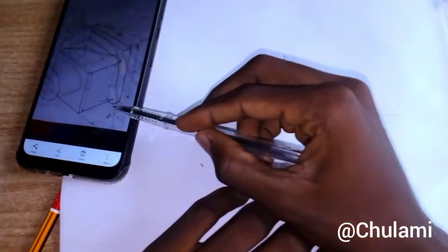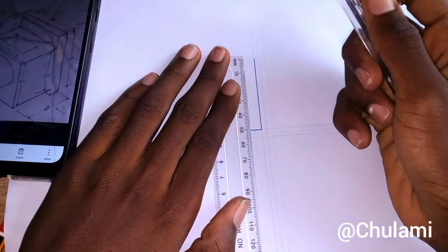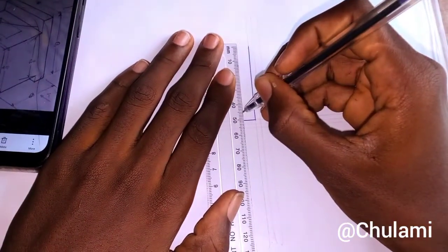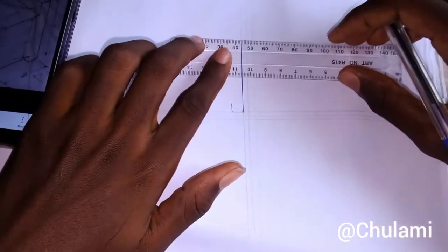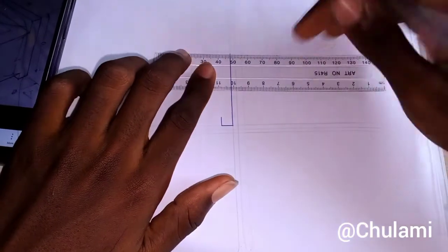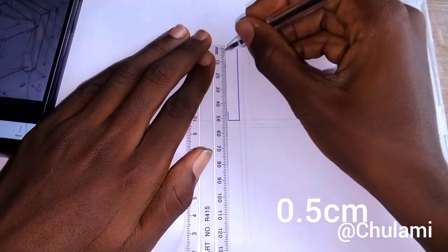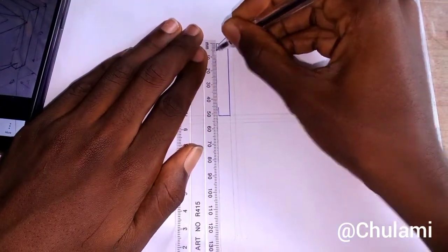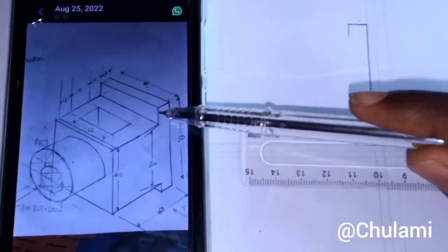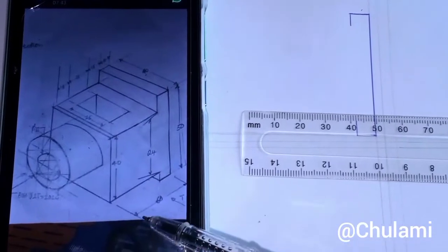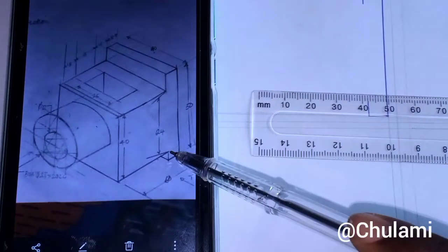And there's a little step up here, which is 0.5 centimeter. Also mark it out, 0.5. Let's do the same thing here, up 0.8 centimeter, and then 0.5. Okay, pause. Now I've gotten this part, and let's draw here. Since here is 60 and we remove 8 centimeter, what we have left is 52. So we draw 52 centimeter.